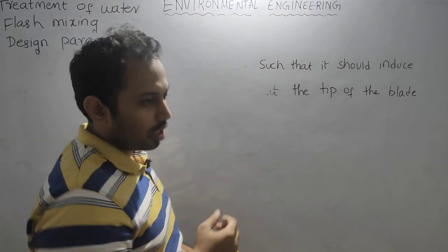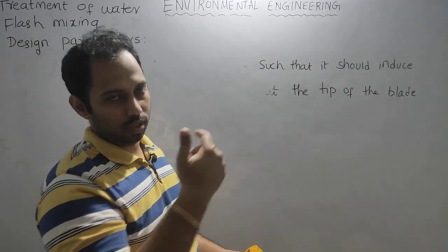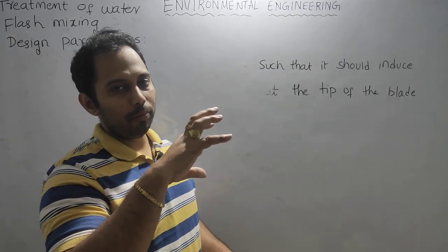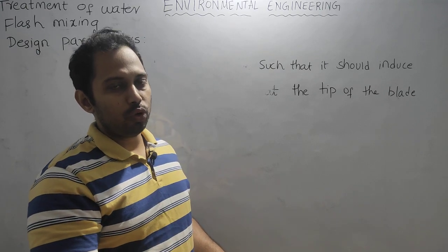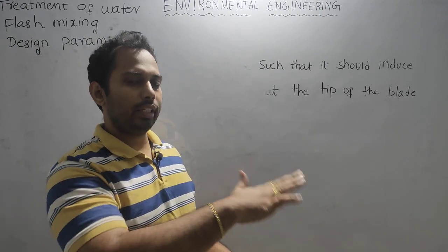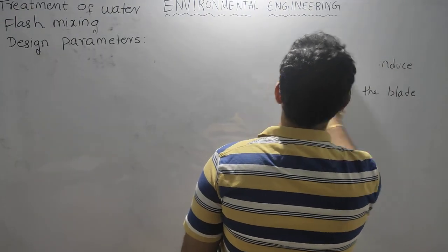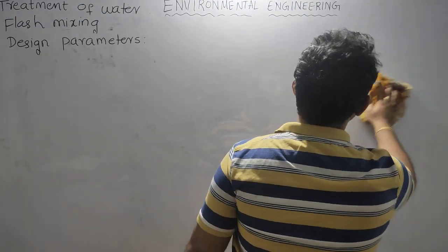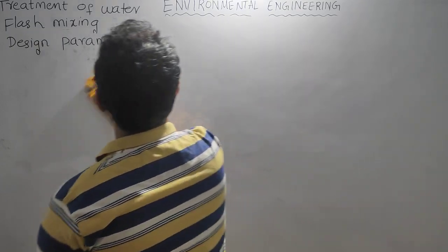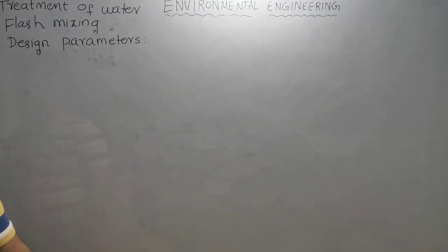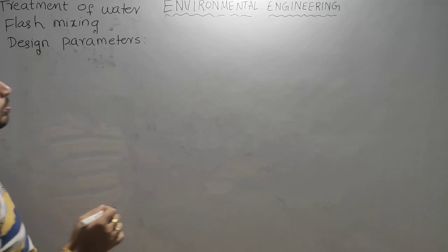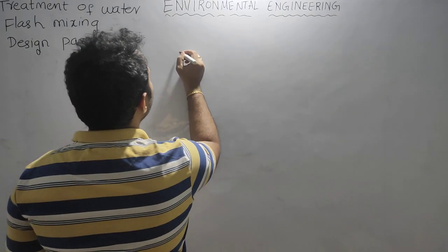So to rotate the water, the blade should drag the water. Then the blade will be offering drag force onto the water. Similarly, the reaction drag force will come onto the blade of the shaft. So let us calculate the drag force that will come onto the blade, or that is being induced into the water. Let us see that from the figure, which I will draw again.